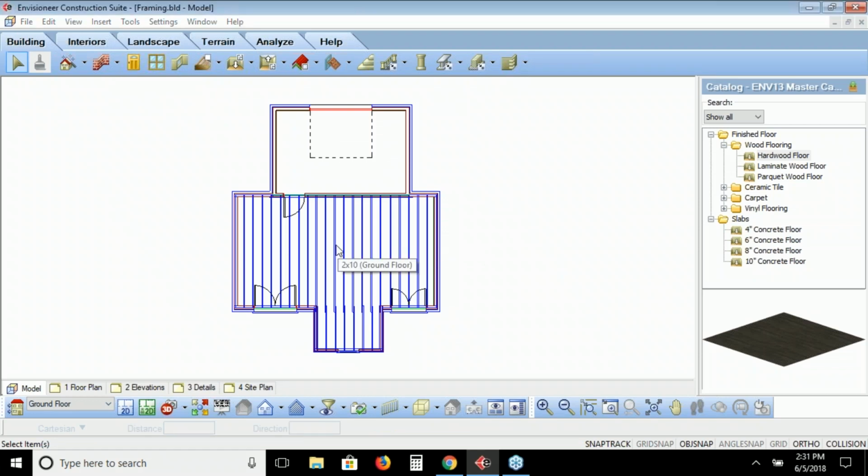I can't individually select the floor joists and modify them if I need to. It doesn't have the insert a bearing line option or the ability to reframe and move edges like I did with this particular floor. So you can frame with Pro Architect and put in a basic framing. You just don't have the advanced structural floor tool.